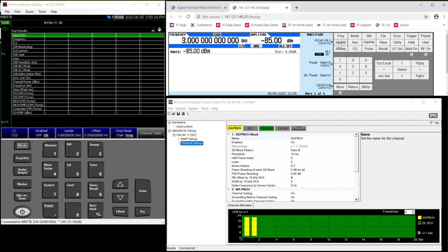Oh, actually, we left the power really low. Okay, let's go back to the original power level, because for EVM measurements, you need higher power levels than that. So if we give this just a minute, there it is. These are your parameters. Now we don't have those bogus 100% EVM numbers. These are clean because this is a clean signal. We're telling it what it is. It's a nice conducted signal.